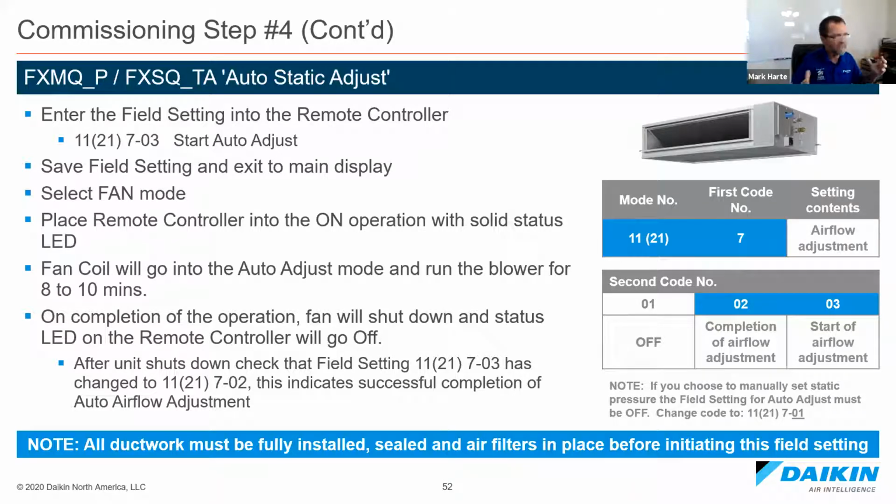So it takes about 8 to 10 minutes. It's going to adjust its static depending on what that fan motor is doing, the amp draw on that fan motor. So that's available on the MQ fan coil and the SQ. Those are the two medium and higher static fan coils.